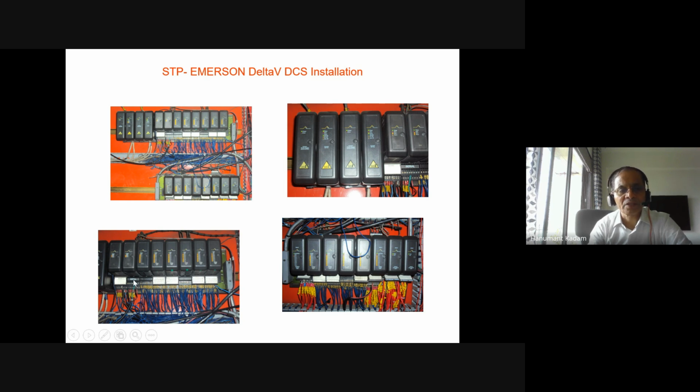The same picture is shown here for this part. You can see this part is here, and above this you can see these are power supplies for the carriers. 24 volt DC is required for the carrier, and above here you can see these cables for power supply to the cards. As I told, it is 5 volt, 9 volt, 12 depending on the controller version, but here it is 5 volt. So this is the system.